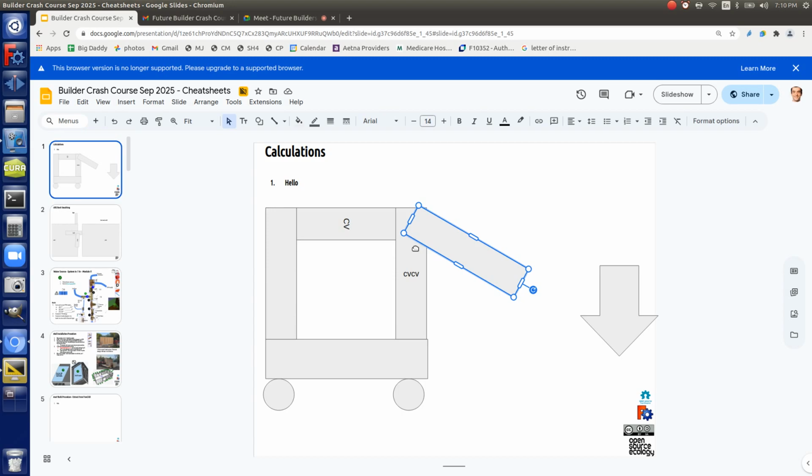Yeah, it is. What's the PSI for steel? It's 50,000 psi for mild steel. Yeah, you've got 200,000 pounds that you can hold. So you know that if you use 4x4 steel tubing, now assuming it doesn't bend, of course you've got to make it into a cubic frame that's solid, and other things. But from first principles, you start with, okay, what kind of material am I going to use? Well, 4x4 tubing is more than enough here. So great, we can go forward with 4x4 tubing, because we know we've got way more than, say, we want to lift 7,000 pounds.